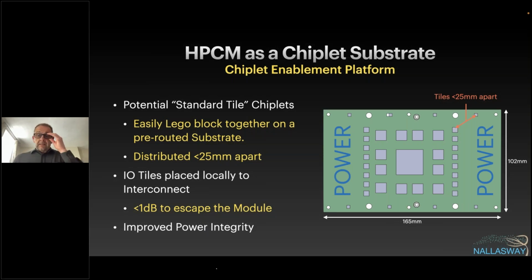But there's definitely... I think being able to connect two modules, assuming the organic area is a little large right now, if you could just go half of that, that seems more reasonable maybe. And then obviously some methodology to connect them. And it does look like the SerDes guys, once one does it, then there's going to be 5 other guys doing something similar, right? Right, exactly. If you look at NVIDIA's NVLink, I think they've got 4 or 5 different PHYs for these different reaches, from chiplet to package to package.